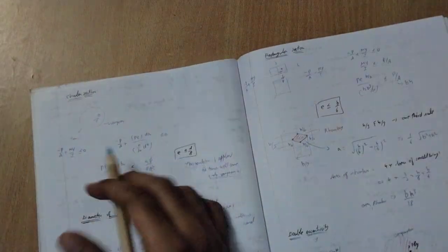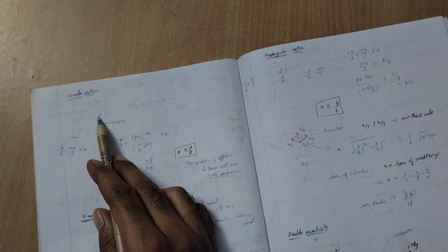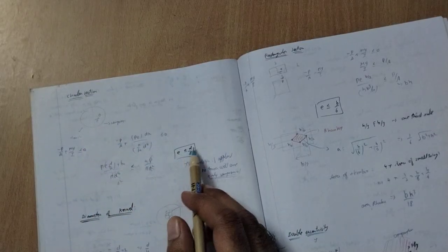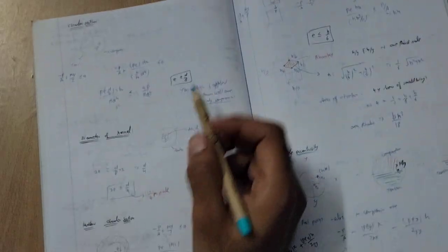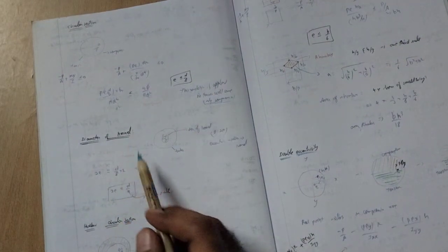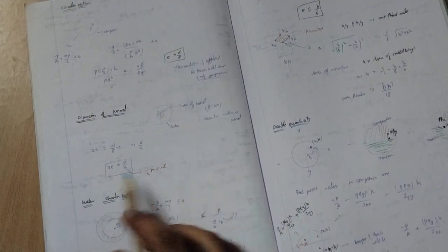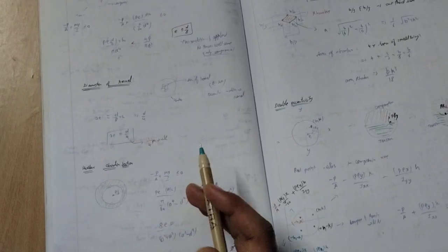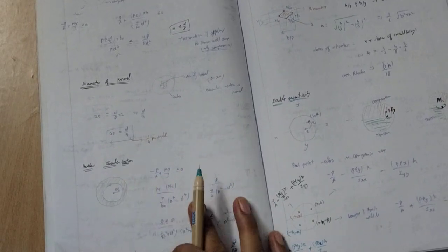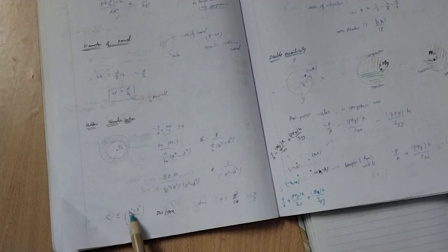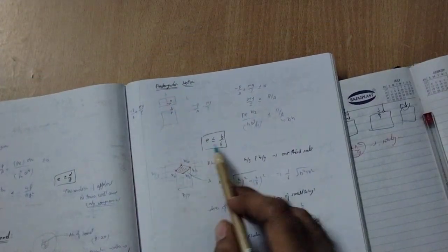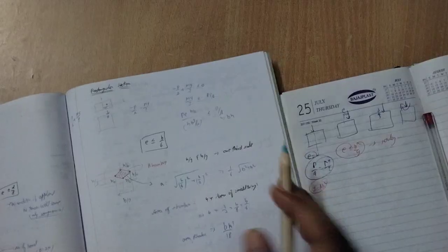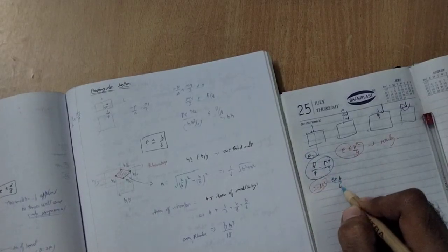So if you go for a circular cross section, you can see this is the eccentricity. For a circular cross section it is less than d by 8. The diameter of the core kernel, you can take e equal to d by 8. For a hollow cross section, you can see e less than or equal to (D squared plus d squared) divided by 8 of capital D. That's it. Whenever you go for a rectangular cross section, you can see e less than or equal to b by 6.